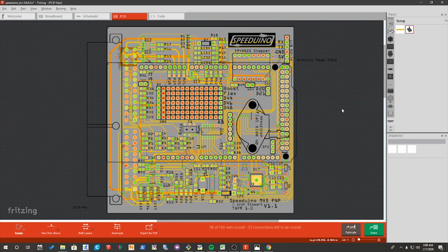So, if we go over to our ECU and check out pin 1B, just like we were checking out on the ECU pinout, if we hover over the pins, the 48 pin circles over here, which is going to be our ECU connector, we can find that this little circle right down here is going to be 1B. And like I told you guys, when you click on these circles, it'll actually highlight in yellow all of the other connections on the PCB where that pin is making a connection with that component.